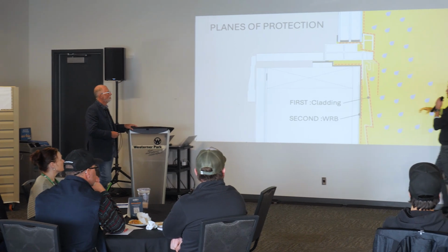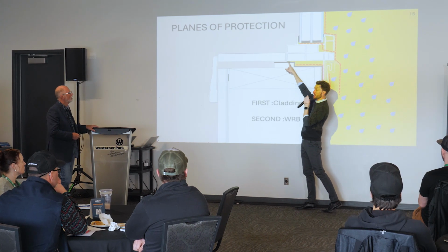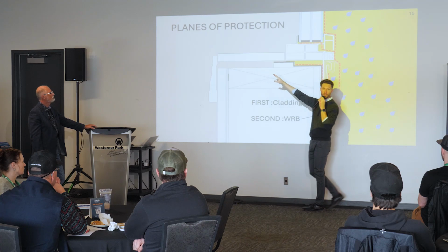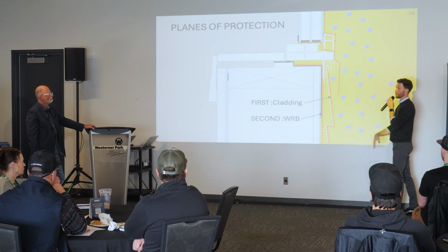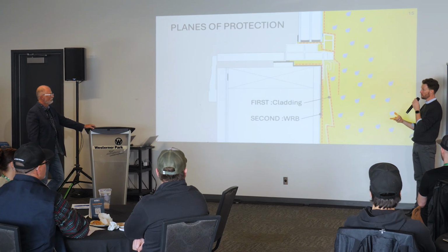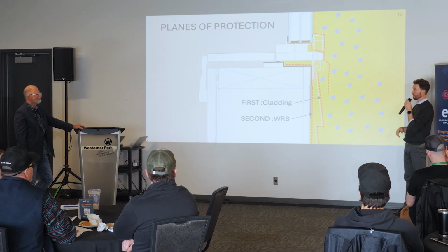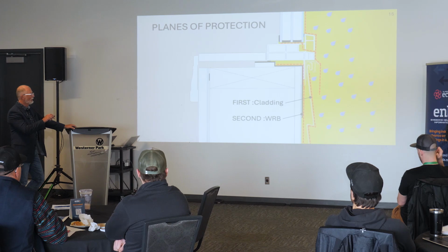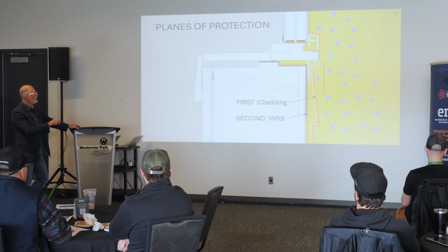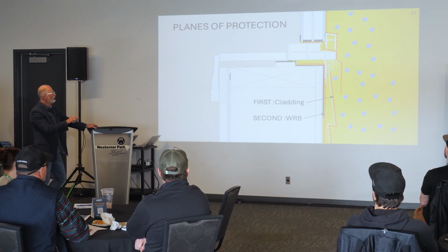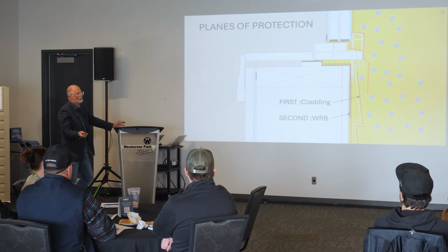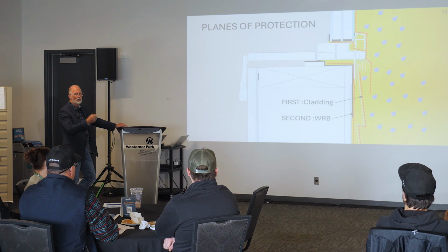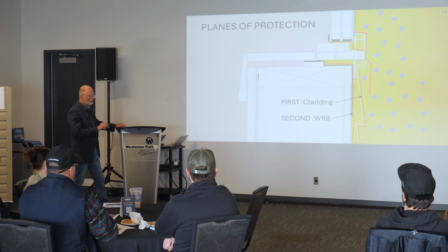And what about a high density insulation material as your back dam? Yep. What if you insulate from here this way? Are we causing problems with that insulation? There's other opportunities. So you just have to be more intentional about how you execute that detail, right? Yeah. You could just take a piece of styrofoam and use that as your back dam, as long as you bring your membrane up and over it, because the window is going to compress that and hold that in place. So you're not worried about whether it loses its adhesion to that styrofoam or not. So those are little things to think about.